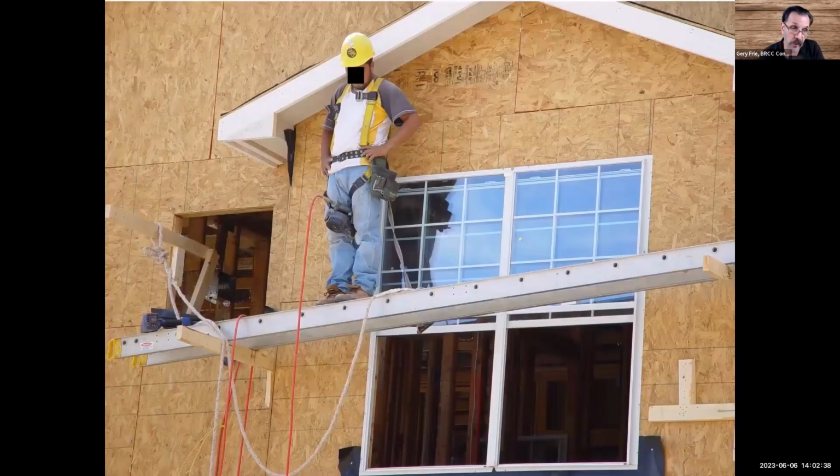His buddy on the other end is in worse shape, though. He's got that white rope that you see here, and that's attached to his lanyard. He'll probably hit the ground before it does anything. And you're supposed to be tied off to something that can support 5,000 pounds per worker attached. So there's that 2x4 poking out that the white rope is attached to over at the left. Does it look like that can support 5,000 pounds to anybody? Not likely. And both guys have the same nail gun technique here.